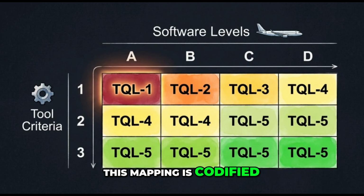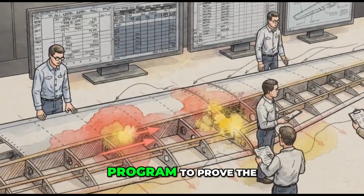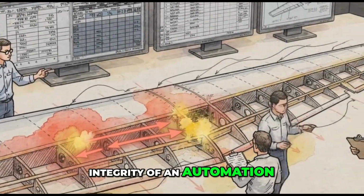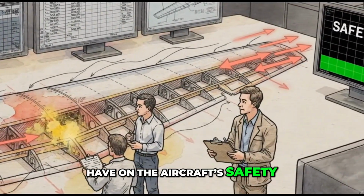This mapping is codified in DO-178C, Table 12.1. Criterion 1 gives TQL1 at level A, TQL2 at B, TQL3 at C, and TQL4 at D. Criterion 2 gives TQL4 at levels A and B, and TQL5 at C and D. Criterion 3 gives TQL5 at every software level. This matrix forces a program to prove the integrity of an automation tool based on the impact a failure could have on the aircraft safety.